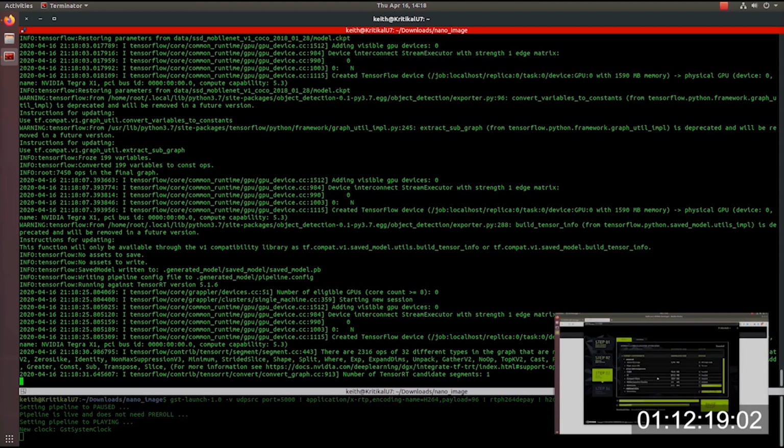At this point in the process, we've downloaded a couple of files, unzipped them, ran a few scripts, set a few things up on the Jetson, and we're just about ready to go. Whereas over an hour into NVIDIA's SDK manager, we still haven't left their website. And this is for a variety of reasons. One of which is because we have to compile our own disk image in their SDK manager, which is really why this whole process is going to take so long on their system, because we have to compile our disk image before we can install it onto the Jetson, before we can install TensorFlow and get everything running. Whereas the Gumstix Yocto image has everything pre-integrated.